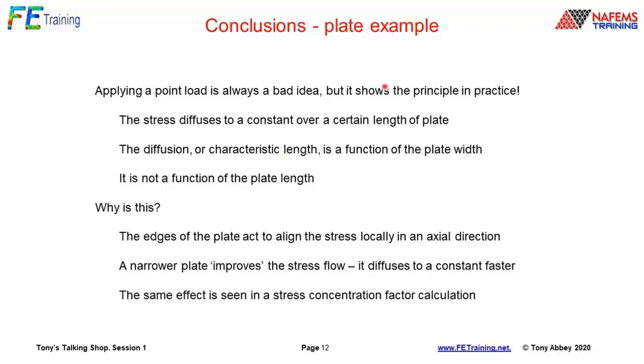Now, why is this? Well, the edges of the plate act to align the stress locally in an axial direction. So as that plate gets narrower, the stress is already entrained to flow tangential or parallel to the edge of the plate. It's a little bit like fluid flow.